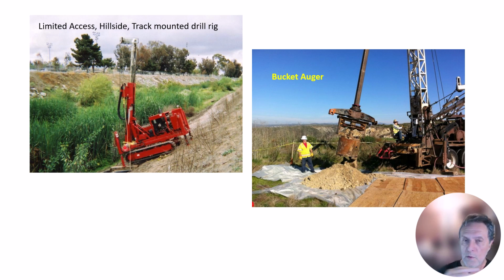But the thing with these limited access rigs, whether it's tripod or track mounted, is they take more time than a regular truck mounted rig, and typically they're somewhat more expensive than a truck mounted rig.